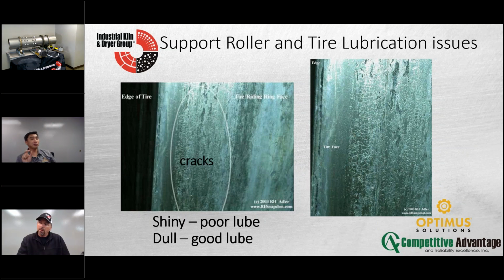Okay, because that is a major problem with oil-based or grease-based lubrication, because when you have that in there and it compresses, you now have a mechanism for failure. The base material mechanism with graphite is its sheets, and the sheets peel off. So the coefficient of friction on it is not as good as an oil-based one, but it's enough that you're not damaging your tire and roller. The goal is just to keep something between a tire and roller, okay?